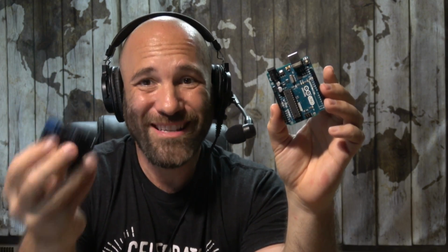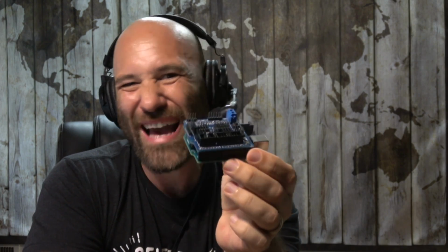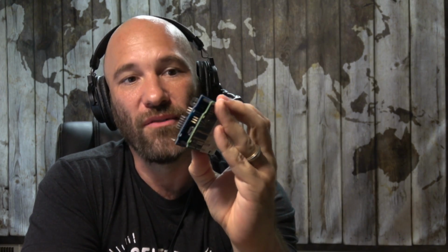Now, whenever you hear about Arduino boards, one of the things you will also hear about are shields. Shields are components that you can connect directly to your Arduino board in order to add functionality to the Arduino. Something like this is a sensor shield. This allows a tremendous number of sensors to be added to a normal Arduino board. You line up the pins on the Arduino board and the shield and connect them together so that it becomes one device. It's sort of like an electronics version of Legos.